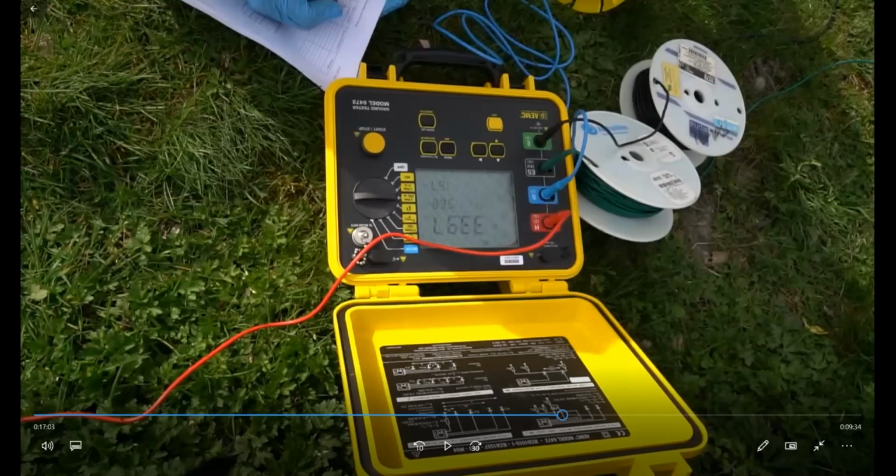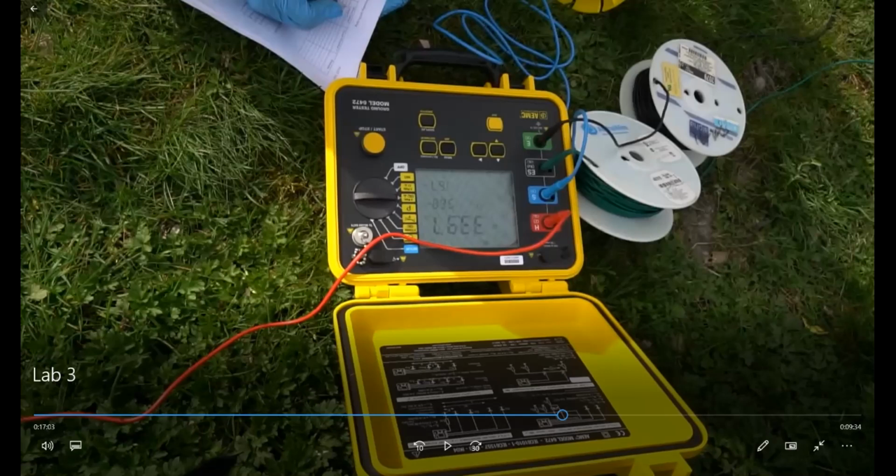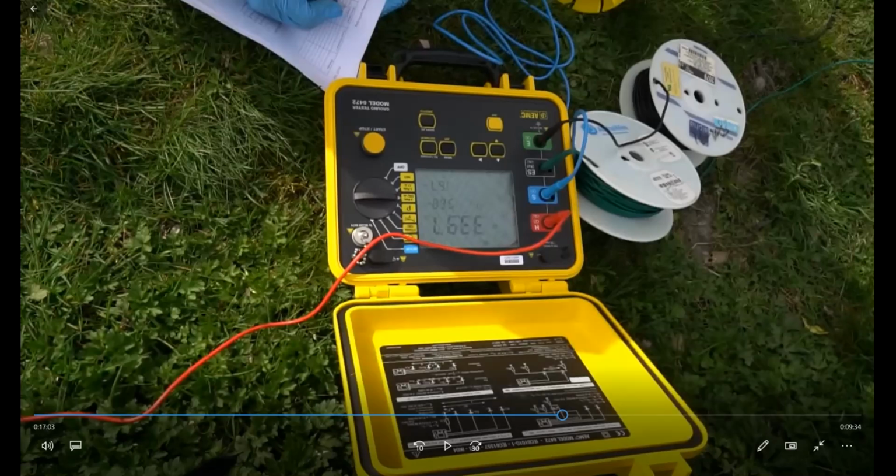Okay, the allowable touch voltage you will have in your model. And the reason is very obvious, because we don't have any grounding grid here. As a result, see, the resistance in a real grounding system will be less than 1 ohm. Okay, less than 1 ohm, and at that condition you will have a different, much lower touch voltage. And when your model is complete and you calculate the touch voltage using your model, you will see the touch voltage will be much lower than the one you have here.